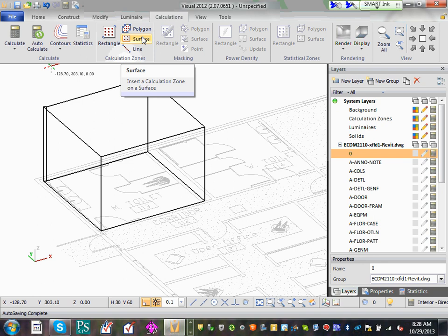You have 2 options. Either you sit it at desk level, 2.5 feet, exactly where you're sitting and working right now, or you can sit it at 0. Desk level everywhere in the plant, except typically hallways, we put them at what? 0. Because do you sit there and read or work in the hallway? Maybe. But the general assumption is everywhere else in the commercial building, we sit them at 2.5, desk level, offices, desk level. That's my calculation zone. Everything else in the hallway is going to be a big fat 0.